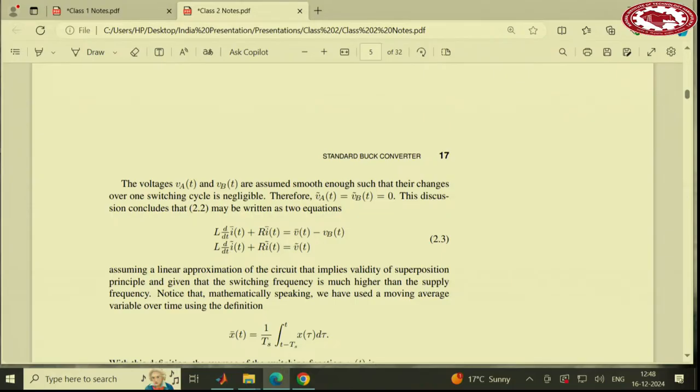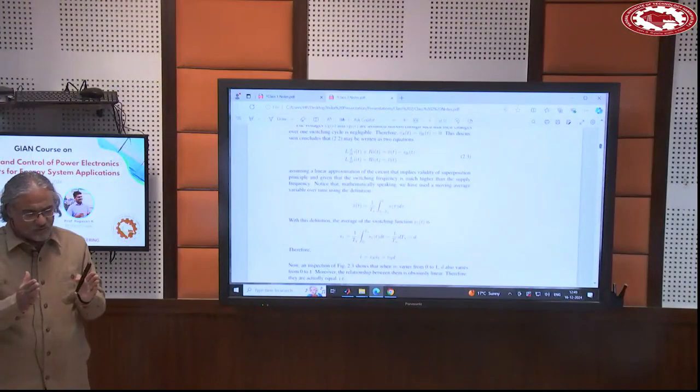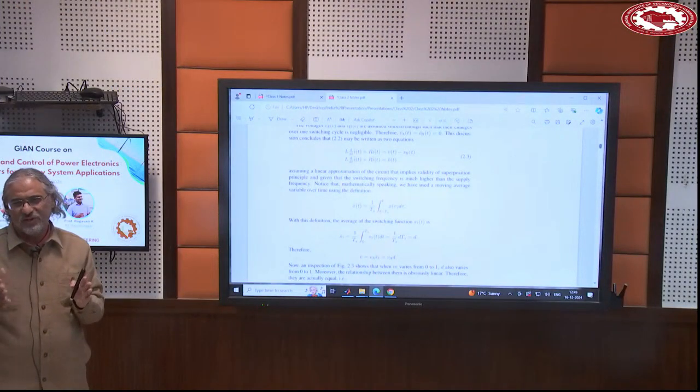So that voltage equation. And the DC part, according to Fourier series, is the 1 over Ts integral of that waveform over one switching cycle. And now that switching cycle, you just move it with time, right? So it looks like you are making average over every cycle. That's why it's called average model. So we say on every cycle, what's happening on average.